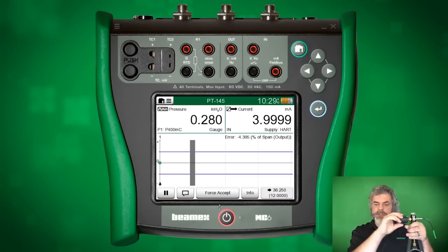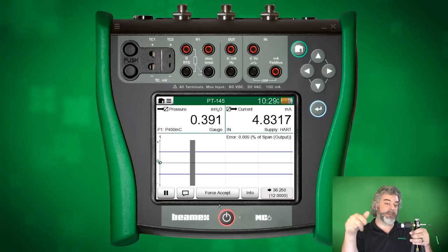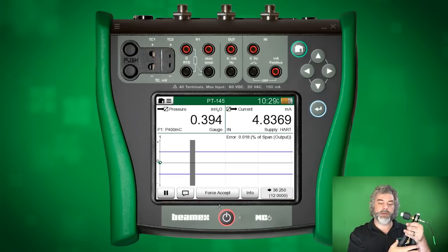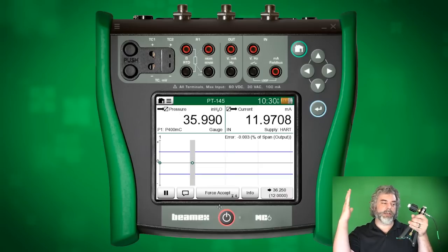So as I increase pressure, and I'm just doing the fine tune knob, we get to a point where, okay, now it's actually not clamping the output anymore. And I'll just gently squeeze on this thing. I could use the fine tune knob. And I just want to get it in the gray area, and I'll let go.